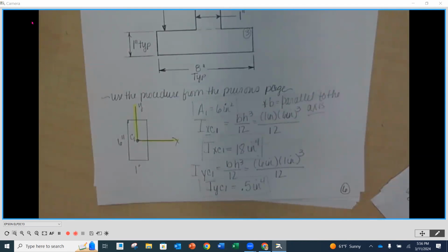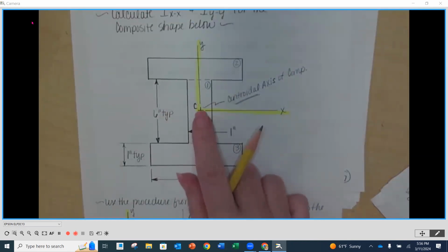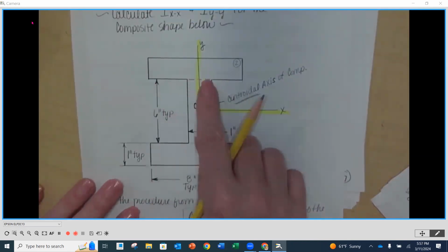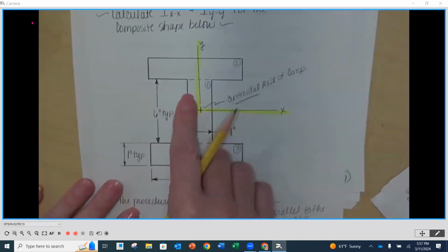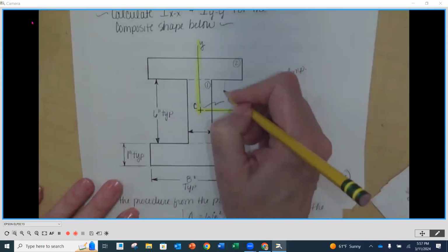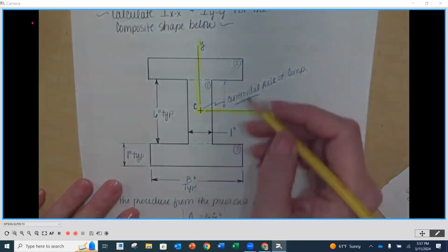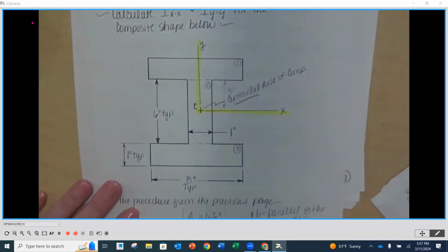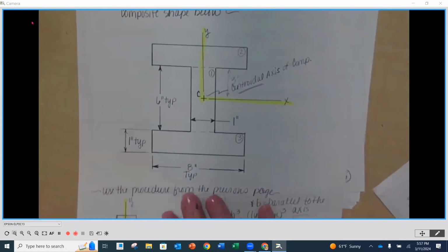All right. So now we're going to move on to our next shape, and we're going to draw it in relation to the reference axis. Now this one is going to be shape number 2, so it's going to be up on top here. Since this is 6 and it's evenly distributed at the centroid, half of that distance to underneath shape number 2 is going to be 3 inches then. So we need to draw this shape on the next page.